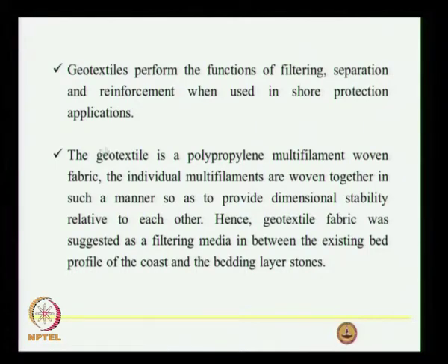What are the functions of the various materials we have used? One is the geotextiles, and they perform the function of filtering. Filtering means allowing the water passage. They also provide separation between the seabed material and the filter material. It also acts like a reinforcement when used in shore protection. If you put a geotextile filter, the whole mass above the geotextile filter acts as a single unit.